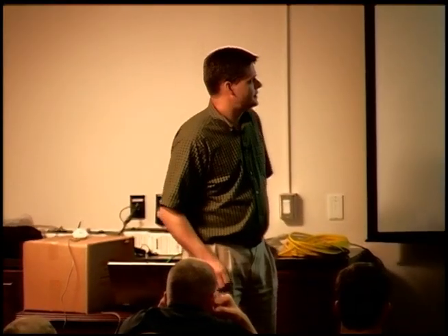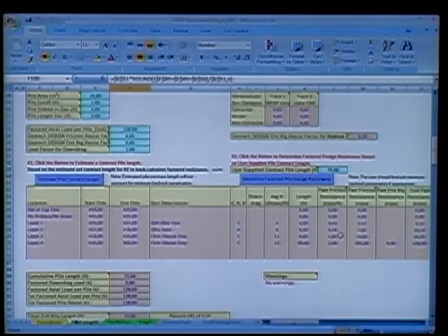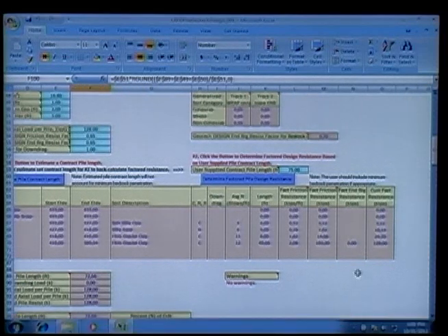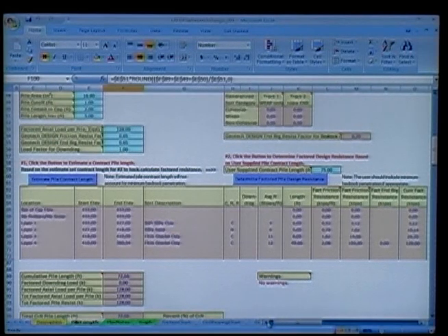And it also figures that out, and it does the kips per foot, shows you what it was using, and then it's the 0.52 times 6 feet should be 3.12 kips. That's what you got in that layer, and it keeps track cumulatively of what's going on. And then you get to the 128 kips, and because this is factored now and not nominal, you can compare it directly to the factored load from the structural guys who figured that out.